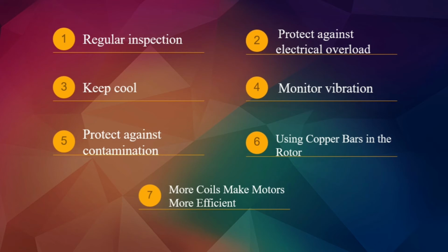However, it can also be caused by short-circuited conductor or an excessive voltage supply. The installation of effective overcurrent protection can detect overcurrent before it becomes a problem, interrupting supply and protecting against overload. This will enable the motor to operate at maximum efficiency.